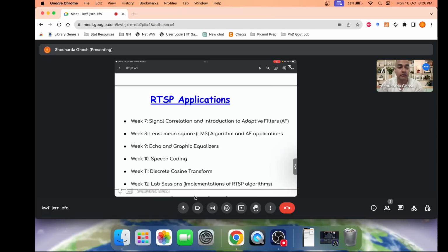Okay, so the to and fro medium, the receiver and transmitter medium, has to be estimated first. And you do not have a good idea of how the system behaves, so that's where adaptive filters come into the picture. In fact, these adaptive filters are nothing but the basis of machine learning and deep learning algorithms. When we talked about adaptive filters in detail, we talked about the cost function, the error curve, gradient descent. And these concepts, if you study machine learning and deep learning, you encounter the same thing.